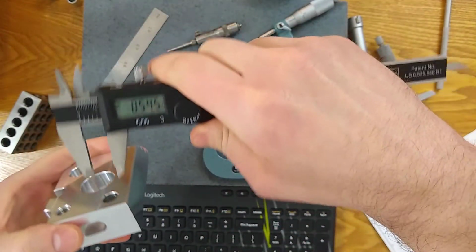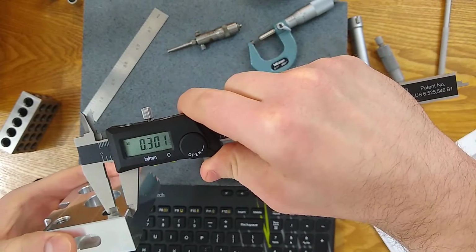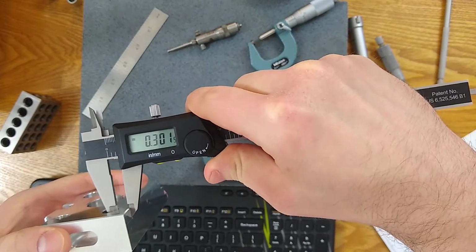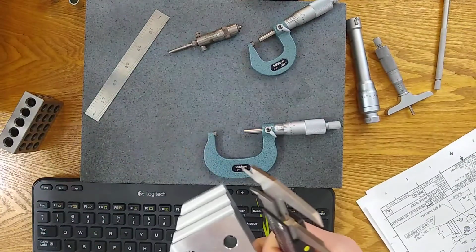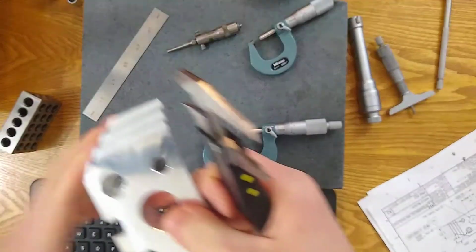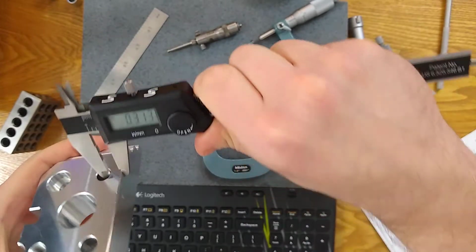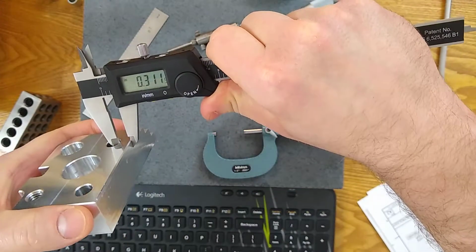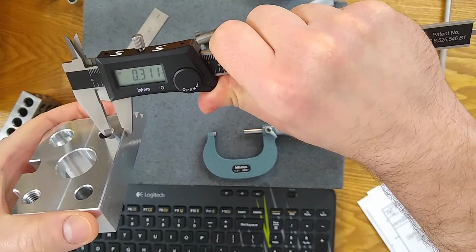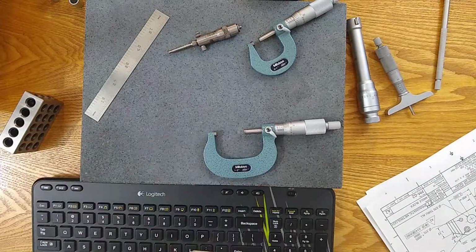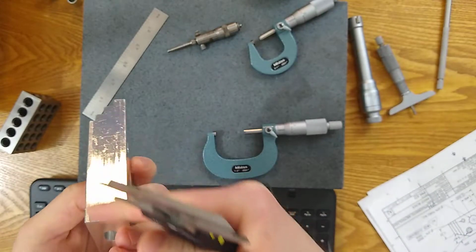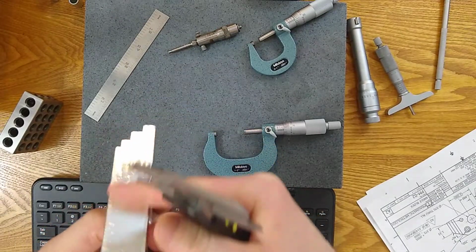You'll often use a caliper, grab the bottom and grab the hole edge, use the distance from the surface to the edge, and then use the radius to get the hole center. And sometimes this surface you're grabbing onto is in bad condition.